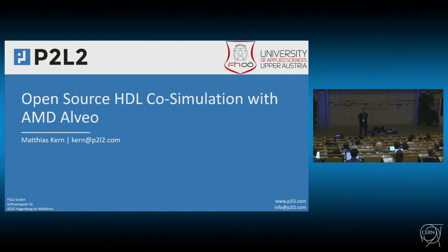No, you don't, because you just offload the simulation design under test. So if you have a simulation, then there are just some std_logic_vectors or std_logics or any other zeros and one values. And you transform this into some sort of representation in a C structure, and this then gets transmitted via PCIe to the FPGA accelerator in binary. So anything that is representable in binary can be transmitted, and then can be a port type. So there are no real limitations here.